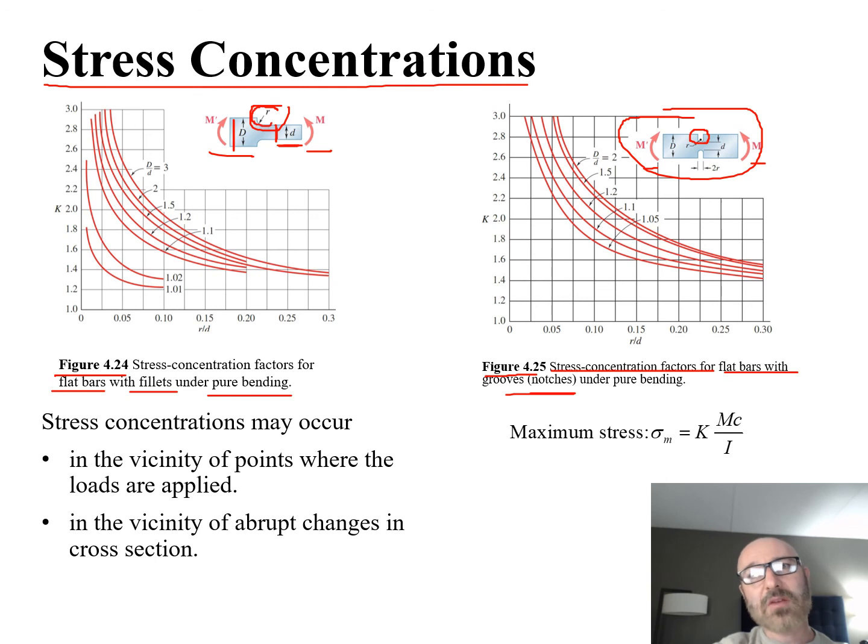And then you have this r value. This is important as we are designing dog bone specimens like that: we want to get that radius, that fillet, just right so that it is not a stress concentration area.